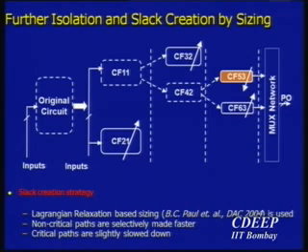In this particular case I'm going to be sizing in a slightly different way. I'm going to size the longer paths to have smaller transistors because I don't care. If it's going to take 2 cycle operations, let it take 2 cycle operations. So I wouldn't worry about it, right? The paths somewhere in the middle, I'm going to size up a little bit. But again, the shorter paths, I don't care. I can make those smaller. So sizing is going to be a little bit different.